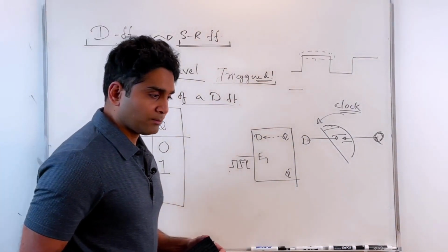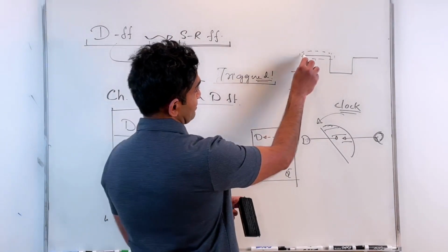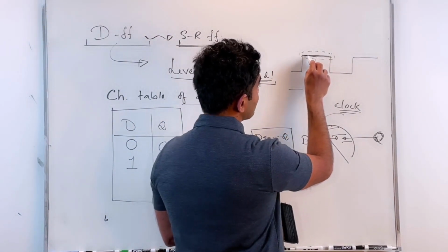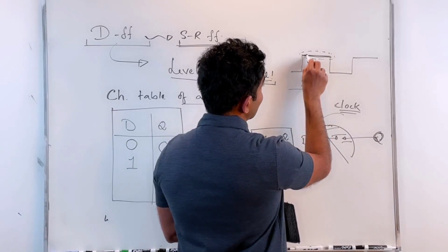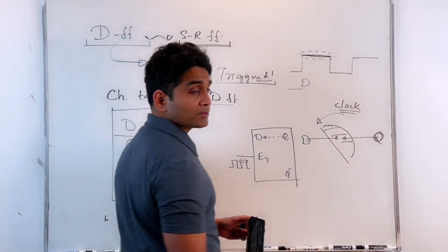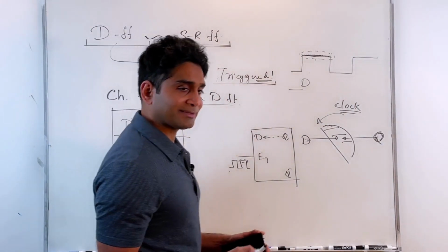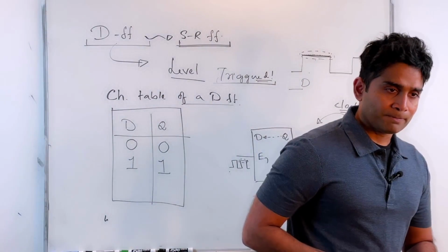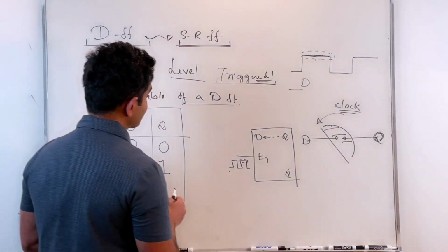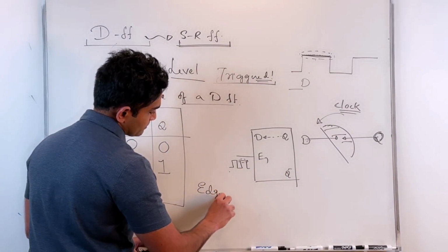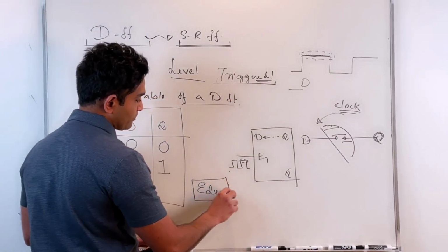And because a level lasts for a longer time, anything can happen on my D during this clock high period, right? We want to minimize that. So we came up with another design of a flip-flop, which responds to the edge, and we call that the edge triggered flip-flops.